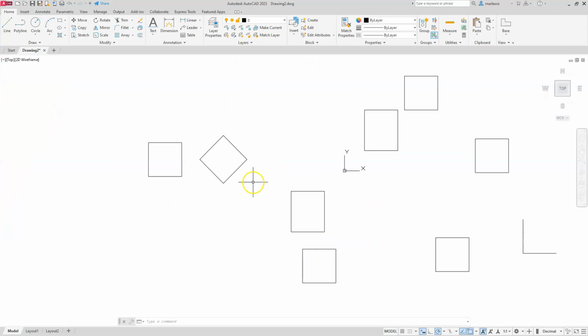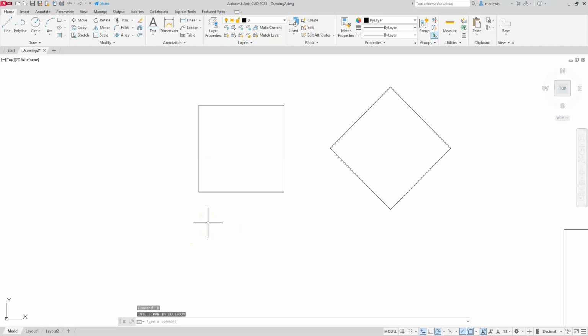Alright, so here in AutoCAD, the undo command is located here at the top. You can also see by the tooltip that the U enter command is the exact same thing as undo. So if I'm in the graphics area, I can simply type U, enter, and it's going to undo backwards. The last thing I did was a zoom function. The redo function appears immediately after I undo something, so if I want to go back, I can redo.